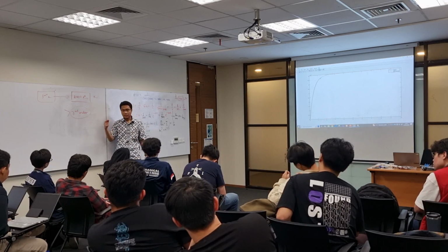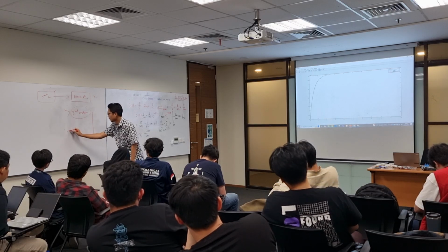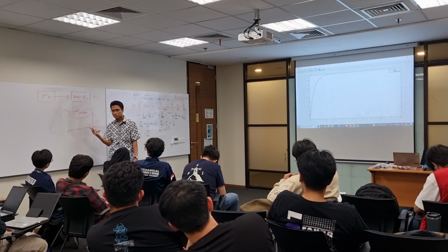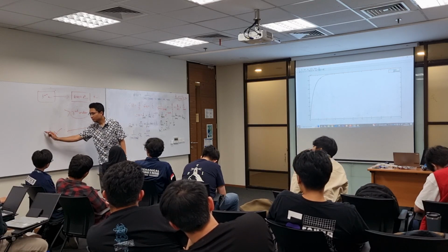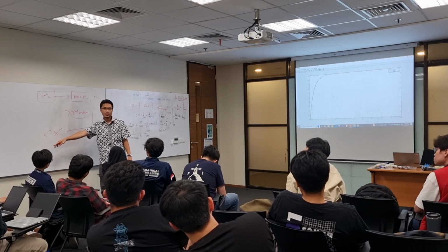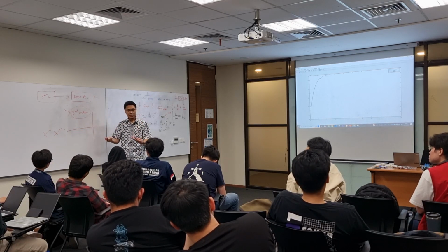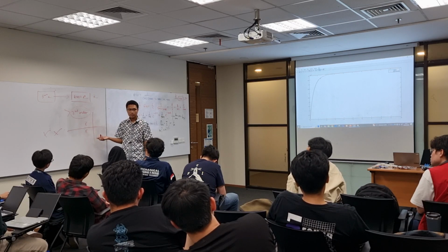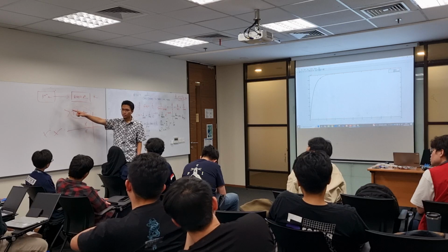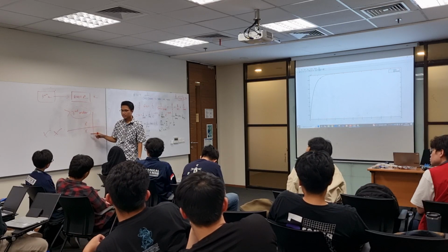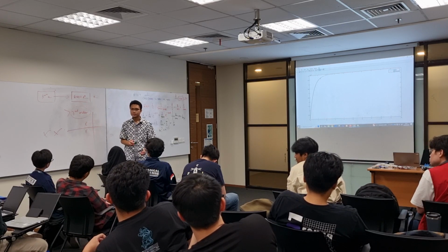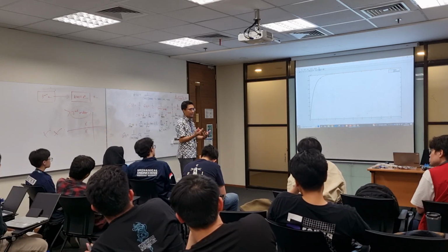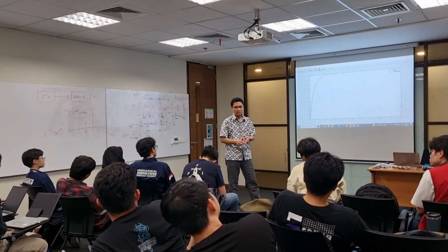Now the way you design it is that when you have your closed loop poles, you place the other poles far away here, and then your desirable characteristic you put over here. You get what I mean? With the correct controller, you can place the poles as you want, because the poles affect how the system behaves.